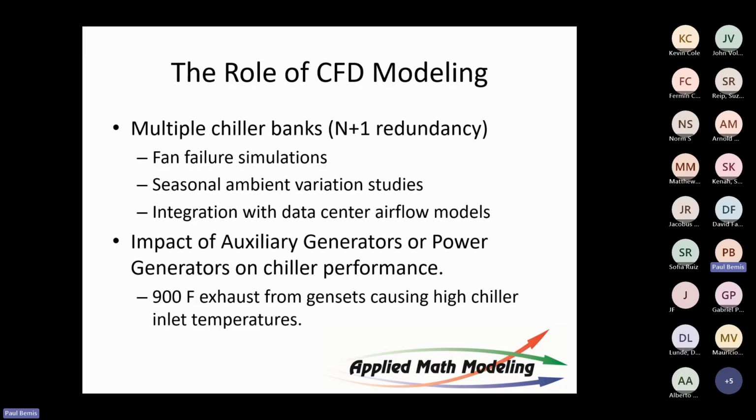Do the internal first, understand what the loads are in the room, understand how much heat you're going to need to reject, and then build a separate model for exterior. Then use the output from the interior model to drive the exterior model. In other words, my total data center is going to be X gigawatts, whatever the number is of total load in the data center. That includes, by the way, the fans. Remember, fans are important.